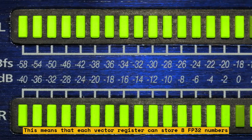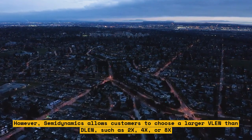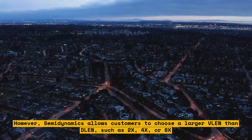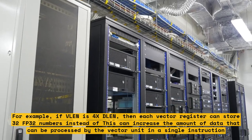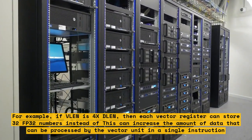However, Semidynamics allows customers to choose a larger VLEN than DLEN, such as 2x, 4x, or 8x. This means that each vector register can store more data elements than the number of vector cores. For example, if VLEN is 4x DLEN, then each vector register can store 32 FP32 numbers.